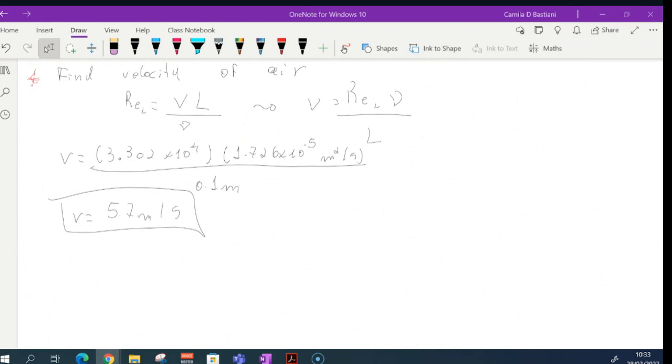I can't remember the Reynolds number in the lab, Alex, because we had very different velocities. We went from 0.5 to 5 or 6 meters per second in the forced convection. I'm not sure all of the possibilities were laminar. I can't remember now. In this case, they were laminar. But here we're talking about flow over a cylinder, not a flat plate. So the relationship is different. This relationship is only for flow over a flat plate. The flow over a cylinder has a different relationship.